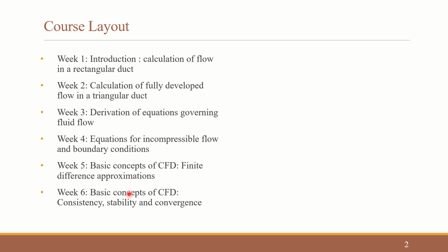We solve for the pressure, velocity, those variables, and for that we need to know the equations. So as I mentioned, it is the continuity equation and 3 momentum balance equations in each direction for problems concerning only fluid flow. If there is additional heat transfer involved in the system, we need to solve for those as well.